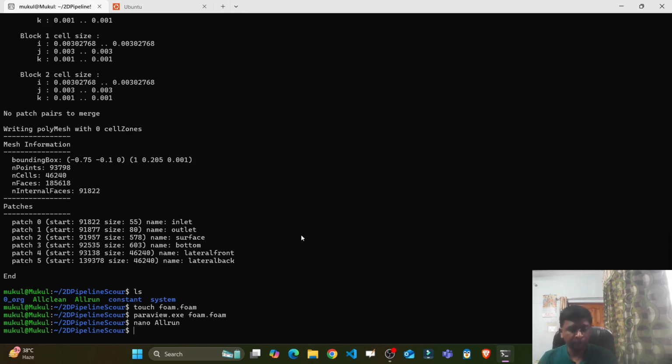Okay, so this is a tip for you all, that you may have done each and every setting well, but it was not giving the good mesh, the good result, because you are not having the optimum number of resources, which means the number of processors, the number of cores in your laptop or computer or the machine you are using for the CFD analysis. All right, so please keep this in mind.